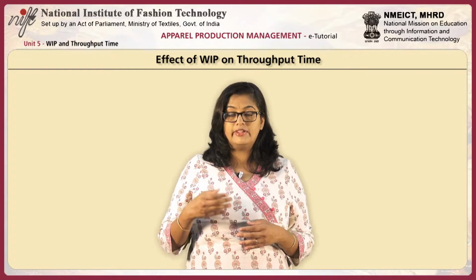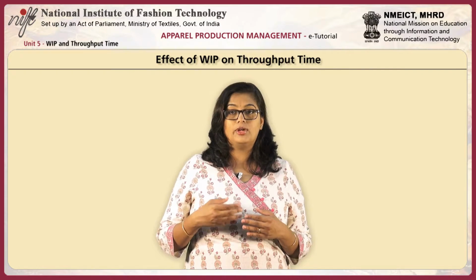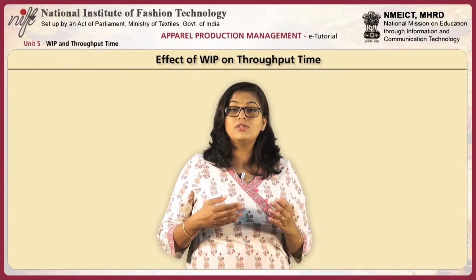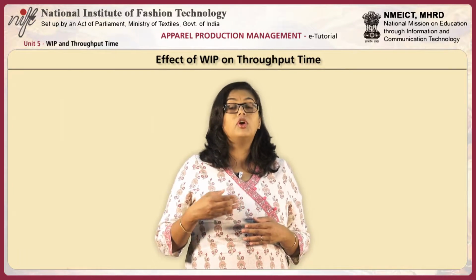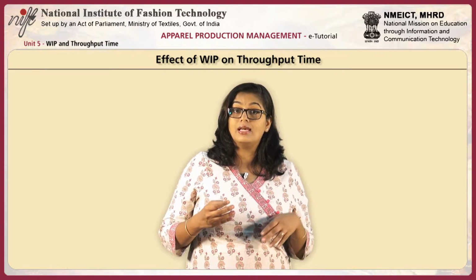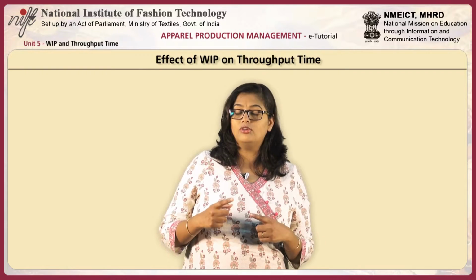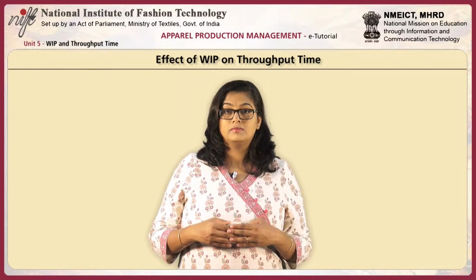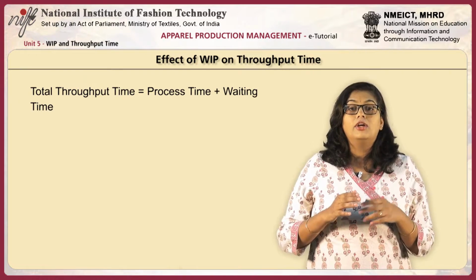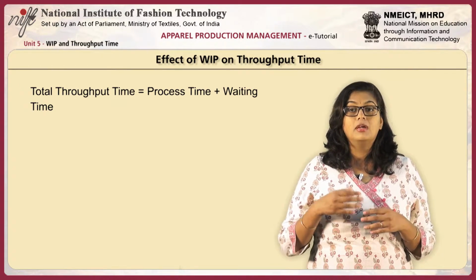For example, between operations A and B, there are 250 garments as WIP. So, after performing operation A, the garment has to wait for 250 garments for operation B, or garment has to wait, let's say in minutes, as 300 minutes. Why? The number of garments into SAM value of that particular garment. Let us try and calculate the time taken. Total throughput time is calculated with the following formula: process time plus waiting time.